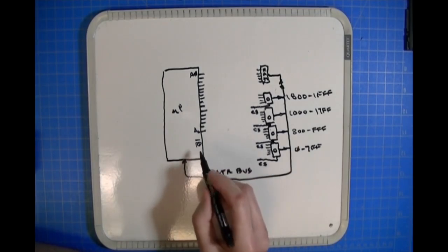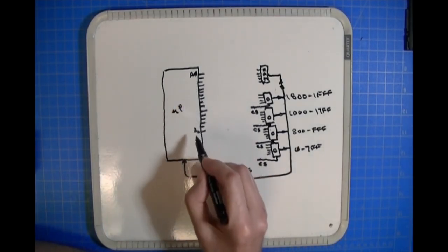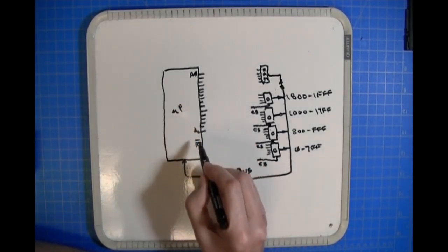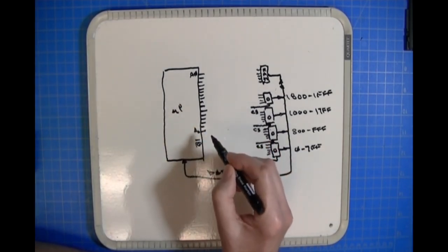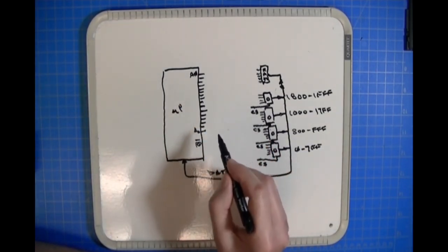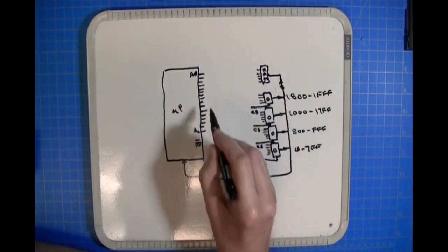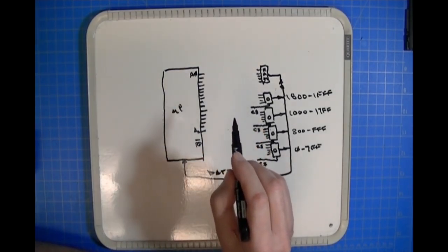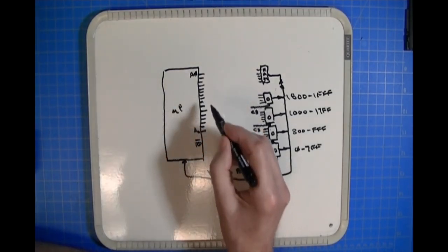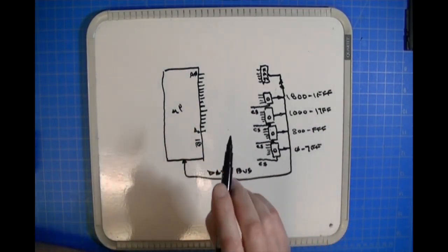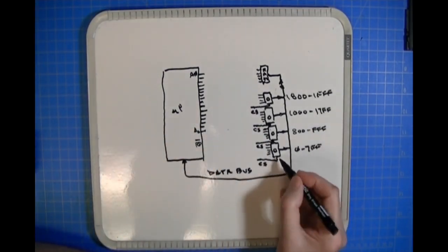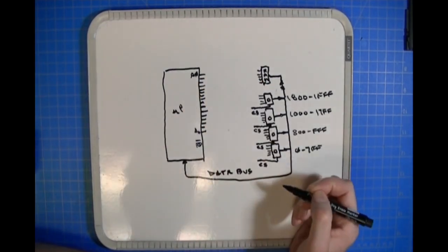All of these lines are address lines coming out of the microprocessor. They're going to be highs and lows depending upon what the individual address is. In this case, this is a 16-bit address. The lines are going to be a series of ones and zeros that point to a specific address. In the case of address 0, they're all going to be zeros.